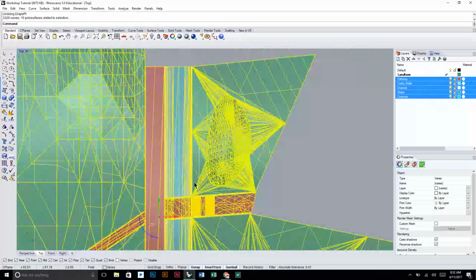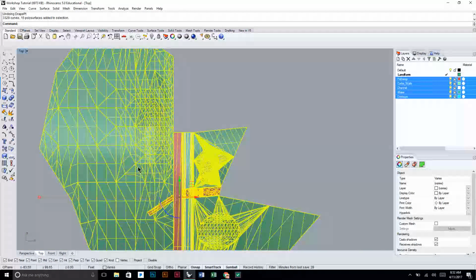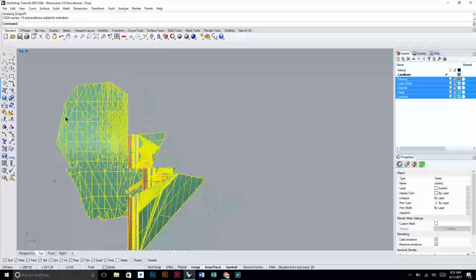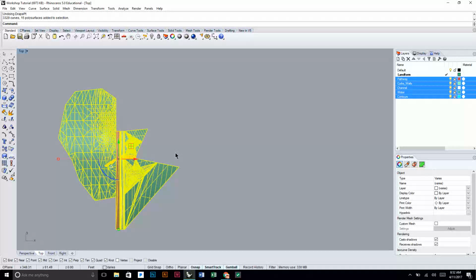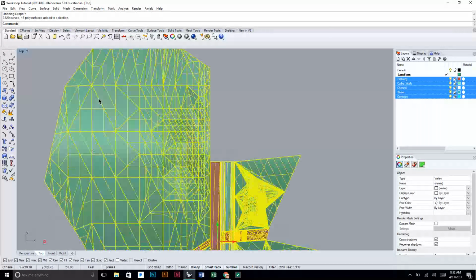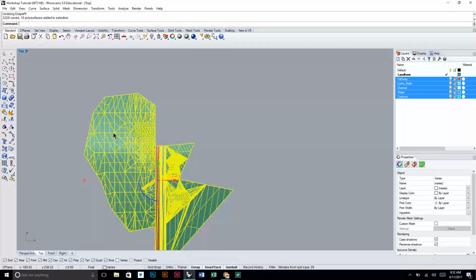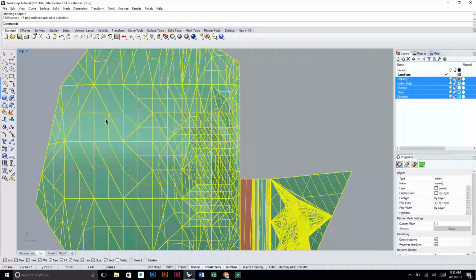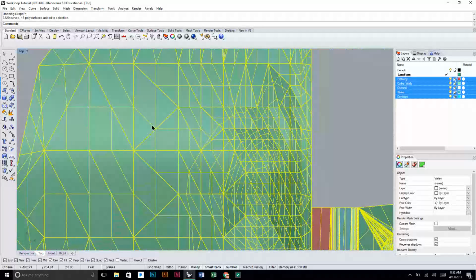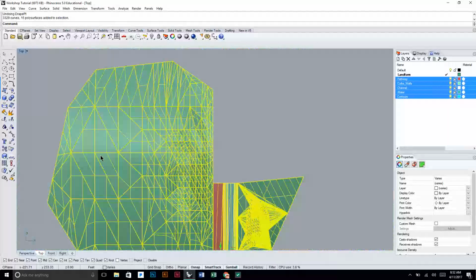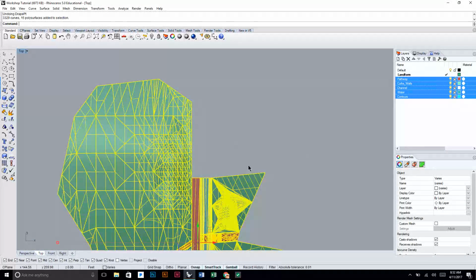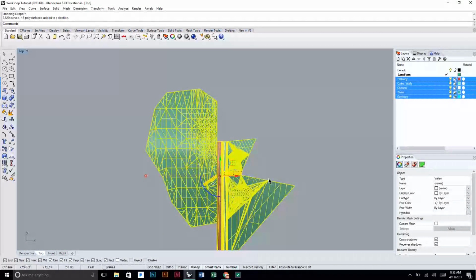And you could technically do the export and essentially extract everything. When you export objects from Rhino to Illustrator, you're only going to get the curves. You aren't going to get an actual surface to work with in Illustrator. And that's something to definitely be aware of, especially when you start to realize that some of these surfaces are made up of a bunch of different geometry. So it's going to actually capture some of that information.